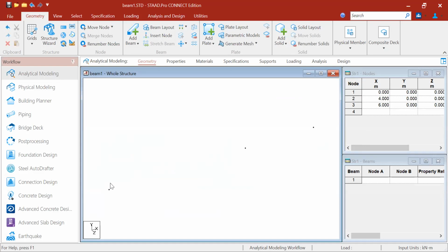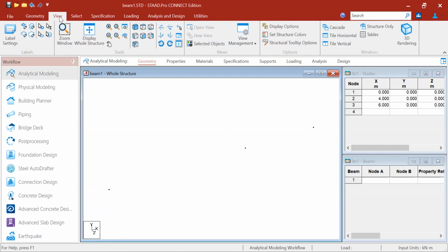Okay, so this is the 2D model, and the default view here is 3D, and you can see the coordinate system. This shows the positive X, Y, and Z directions. I think it's easier for a 2D model to just see the XY plane. So how do we do that? We go to the top menu, View, and under View you can see the cube with the face highlighted, and we select this front view. Click that, and then you will see that we only see the XY plane.